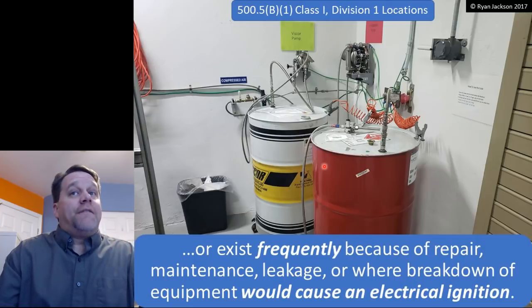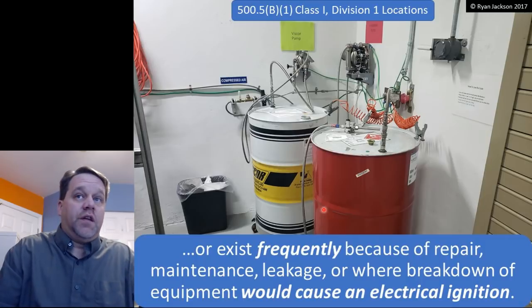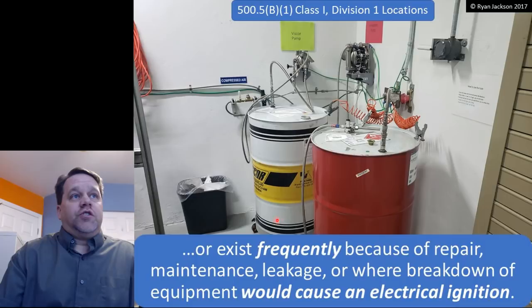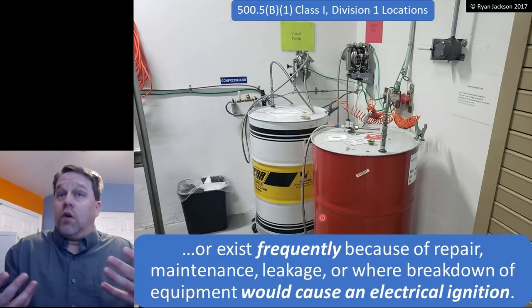But for a half hour of every day, I go in here and I replace these drums, and I have to open the drums while I'm doing that, so I'm releasing vapors into the atmosphere. So I have an ignitable mixture that exists frequently because of repair or maintenance or leakage, right, or the normal condition.